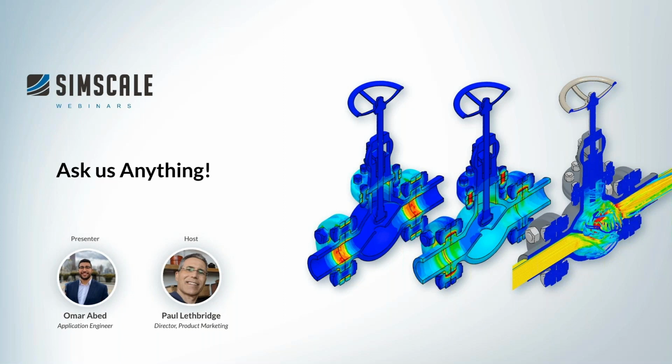So I assume CV is related to flow coefficient. You're able to use the result control to take out the properties that matter, like the pressure drop, for example, that I highlighted. You'd highlight the two faces, the inlet face and outlet face, that you want to define as your reference for the pressure drop.